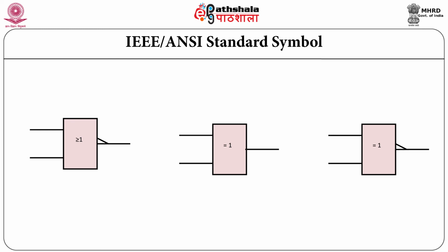In addition, a special notation inside each rectangular outline describes the logic relation between inputs and output. The number 1 inside the inverter symbol indicates a device has only one input, and the polarity indicator at the output indicates that the output is active low.